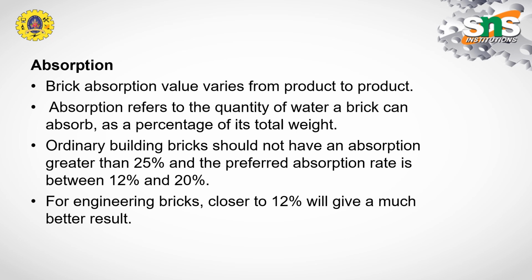It shall not absorb water more than 25 percent. If the brick absorbs water within the limit of 12 to 20 percent, it is a great property and a good brick.